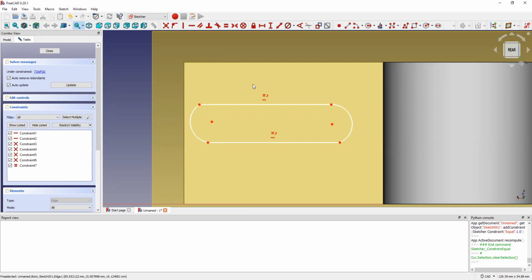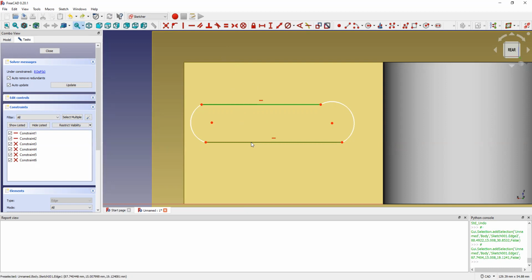Hello? Unanielewa? Yes. We have done our sketch to join the parts. So we want to ensure that this part and this part ziko parallel, yeah? So click all of them, they turn green. Then what next? You click on this symbol. This is to ensure that the constraint is parallel. Unaona?